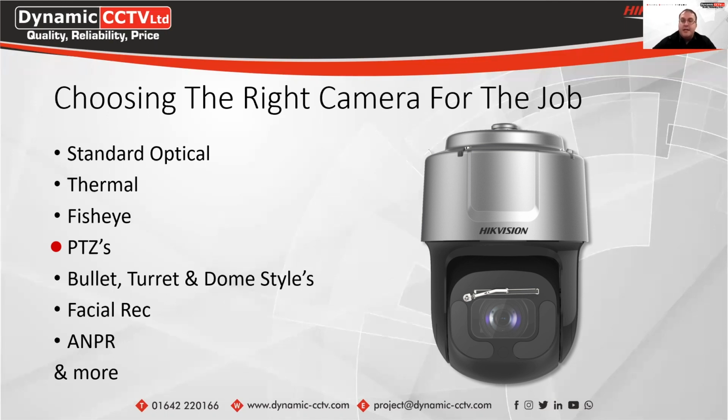We do see a lot of sites where they'll use multiple cameras in conjunction. For example, you could have thermal cameras monitoring your perimeter fence. If anyone crosses that fence line, you can have that trigger PTZs on site, so you can actually see that person. The PTZs would spin round to that location where the line crossing or intrusion detection on the thermal camera has been triggered, so you can get that actual overall image view of that alarm being triggered on the system as well.